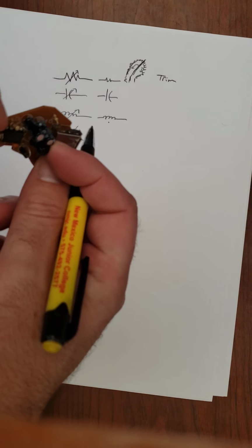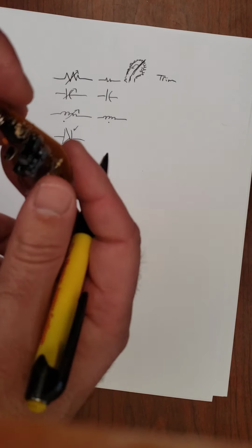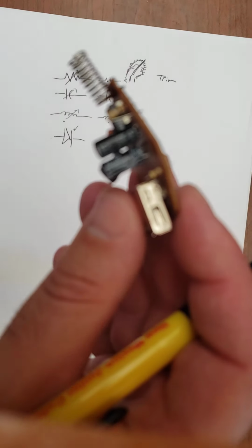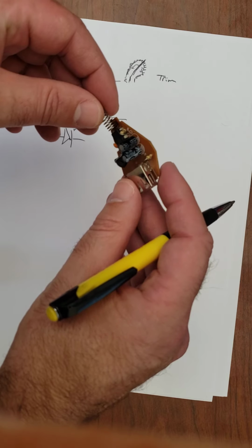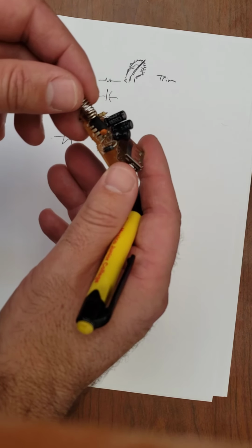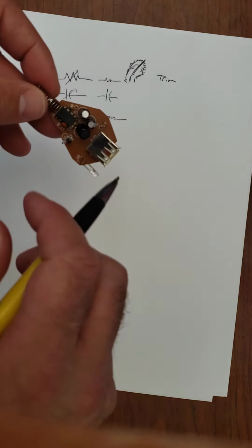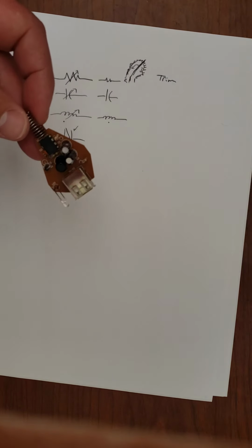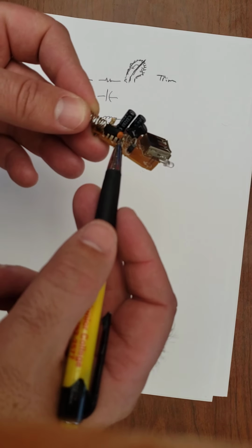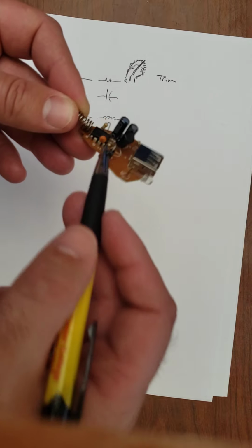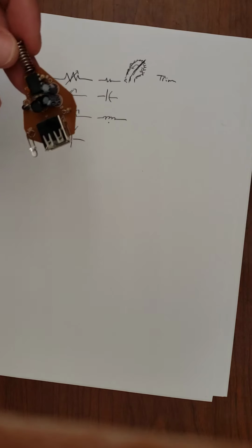You have a couple capacitors on here as well. These big circular things are electrolytic capacitors. We'll talk about those later on. The big thing I want you to notice with these, though, is that if you look really carefully, you can see there are negatives on them, and positives on some of them. While resistors didn't care which way you put them in, and disc capacitors like that little ceramic piece don't care which way they go in, these electrolytic capacitors have a polarity, and you have to keep track of that.